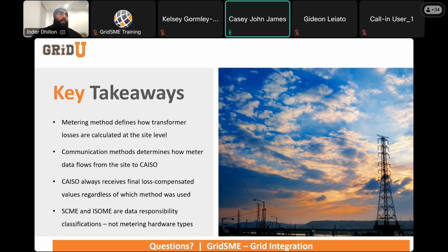If I could jump in here too, I do see that this question is about compensation for the BESS and BESS aux for an integrated system. If the BESS aux load is behind the BESS meter, such that BESS and BESS aux are aggregated at the meter, compensation will apply at the POI, no matter if it's accounting for BESS aux or the netted value of the two.